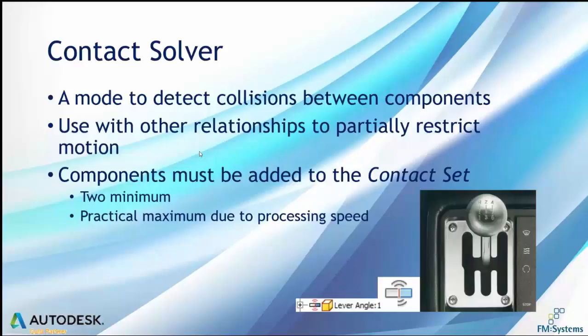The problem is that the CPU has to calculate for every movement, so every pixel that you move an object, it has to recalculate its position to make sure that it's not clashing with anything. If it has to do that with multiple components, it increases the time it takes to calculate. It means that you could move through an object without realizing it, because it's still busy calculating. So let's quickly take a look at how that actually works.